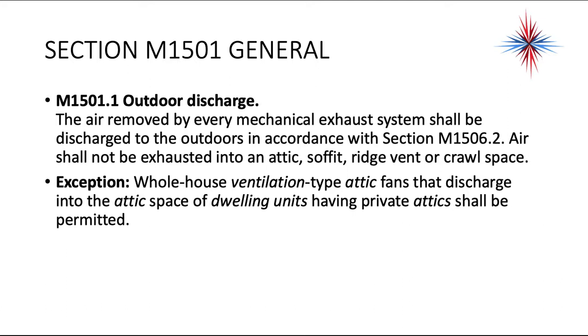There's one exception. Whole house ventilation type attic fans that discharge into the attic space of a dwelling having private attics shall be permitted. In other words, if you have one of those whole house ventilation fans in the ceiling of like a second or first floor that you could turn on to cause ventilation, you're allowed to discharge it into the attic space only if it is an attic that is private to your building.